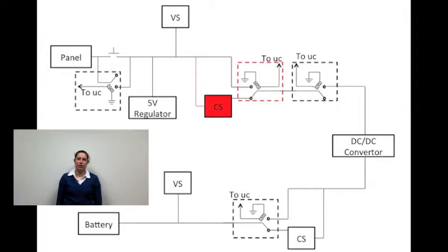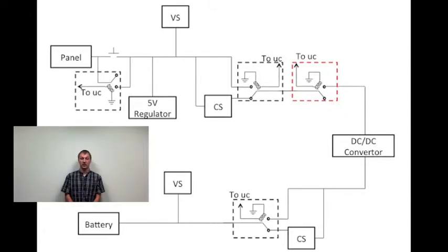The current sensor requires a reference voltage taken without current flowing through it. To implement this, we use a relay to divert the current path from going through the current sensor. A temperature sensor on the evaluation board for the microcontroller is used to monitor the internal temperature of the enclosure. The third relay on the input side of the system is for overvoltage protection. When a voltage at the input is above 40 volts, this relay opens the current path and cuts power to the secondary side of the system.